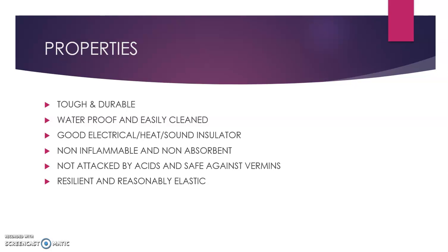If it's not elastic, what will happen? When you use it on roads, the roads are subjected to heating whenever there is hot sun, and then in the evening the temperatures go down again by 7 to 8 degrees. So you need these kinds of elastic properties in all the bituminous materials so that they heat and contract, and when they heat and contract, there should be no cracks developed on the surface. The moment cracks develop, the water will start seeping down.